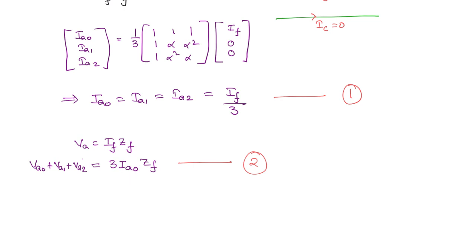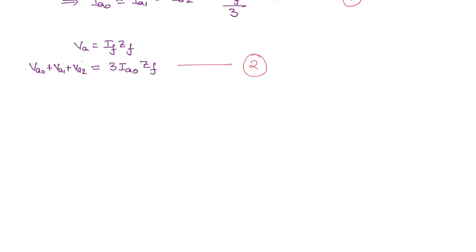Okay, so here also we see that this is a series connection. So first we will draw the series connected sequence networks. The positive sequence network will have the internal voltage as well, because the transmission line will be driven by some generator, right? And here let us say this is the positive sequence impedance. So this is the positive sequence network. The voltage here is VA1 and the current will be flowing out like this, IA1.